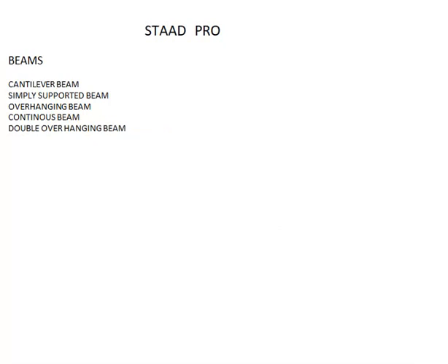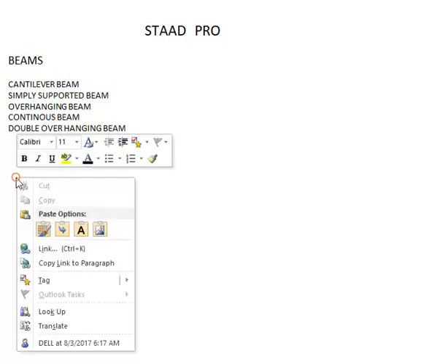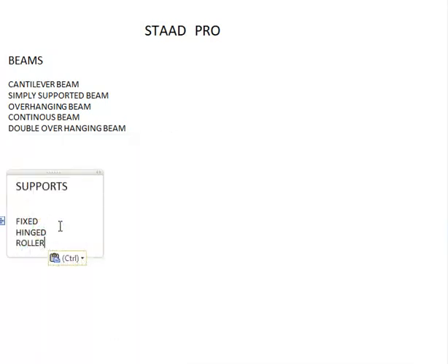Next, we are going to discuss supports. What kind of supports are there and how are you going to use them? So there are three different kinds of supports: fixed support, hinge support, and roller support. For fixed support, there will be three reactions, because if a beam is fixed, it can neither move to the top side, nor move bottom, nor rotate.